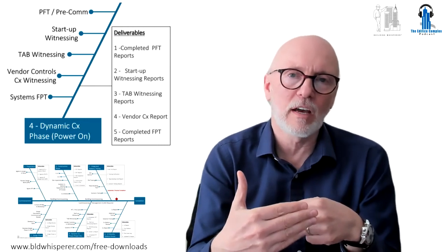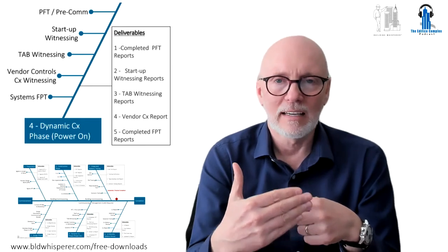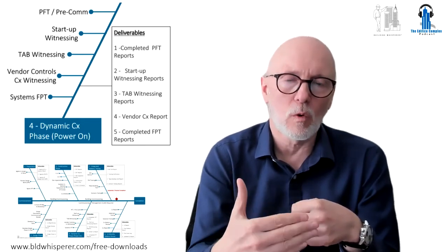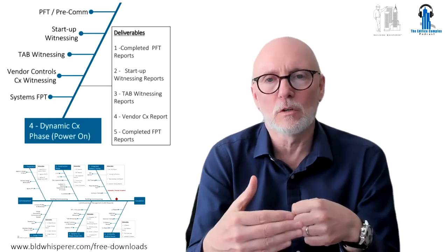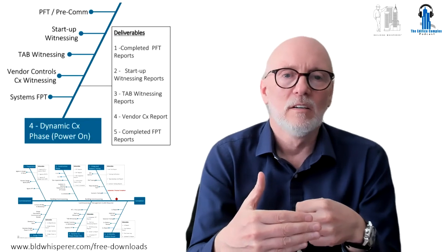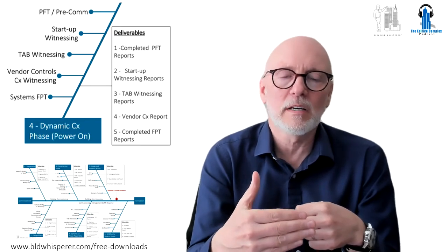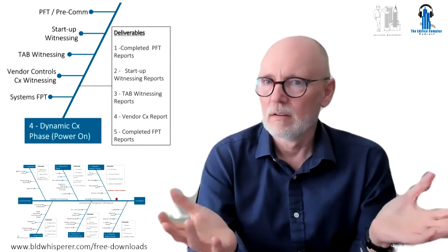Right? It is the verification of the performance and operation of a system. And again, I stress system, not equipment. Just using a crane and putting an AHU on the roof and starting up the AHU, that is not commissioning, that is startup, okay? So commissioning is systems-based, not equipment-based. It is the whole thing. Simple, right?